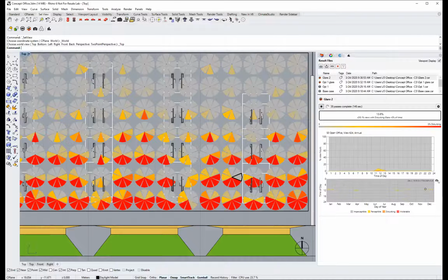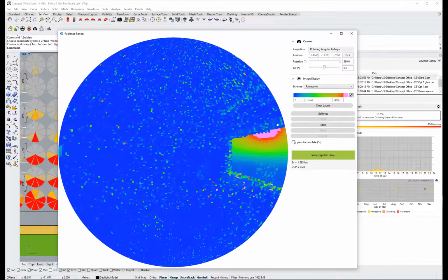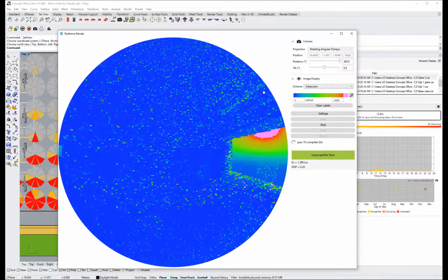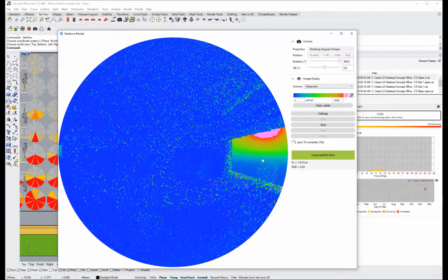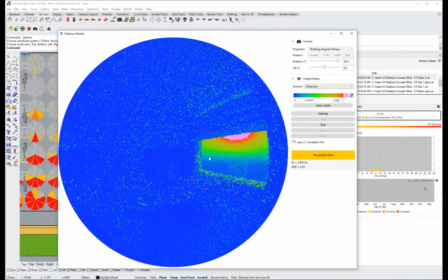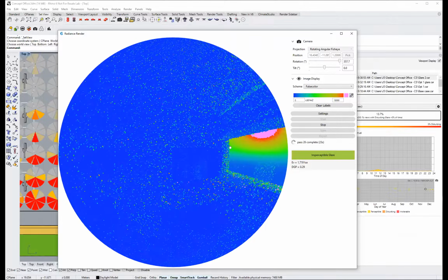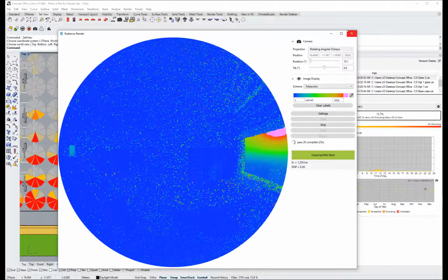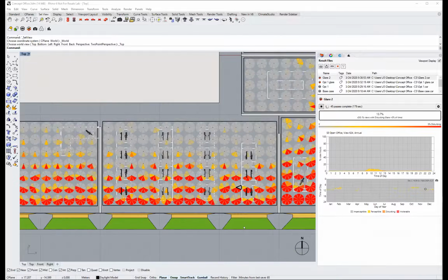So if I go back and just visually inspect that same time point that was causing issues before, what I'll see is a very different story. That bright circumsolar region is now getting blocked by the light shelf and the louvers, right? And so what used to be disturbing or intolerable is now imperceptible. If I rotate and look right at the window, maybe it's an issue, but the way I've laid out the workstations, that's not a problem. So I'm pretty satisfied with this design, even sitting next to the window. We don't really have problems here.